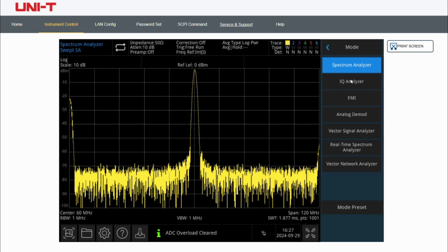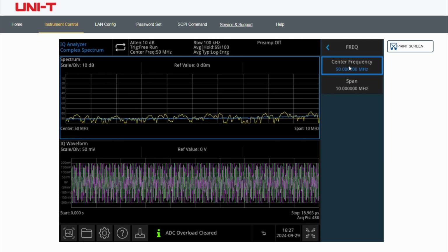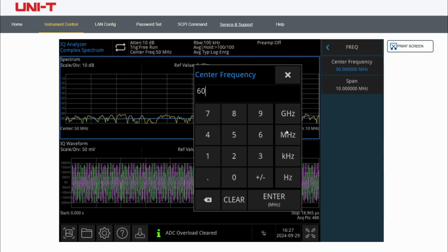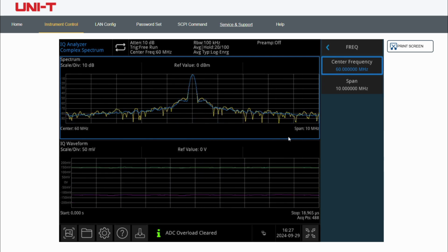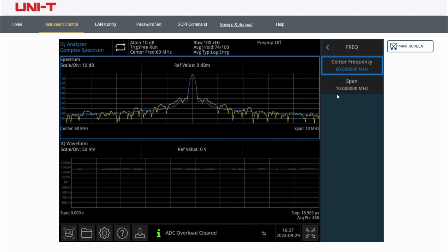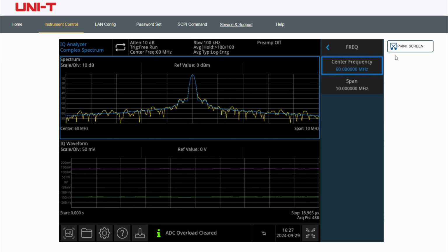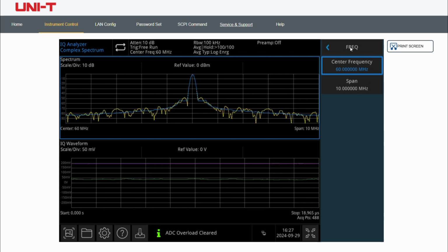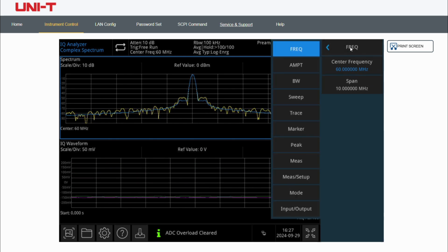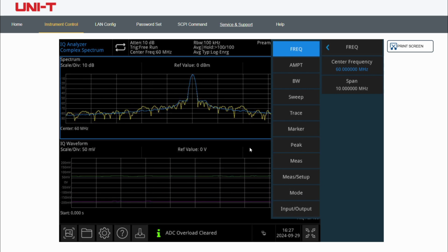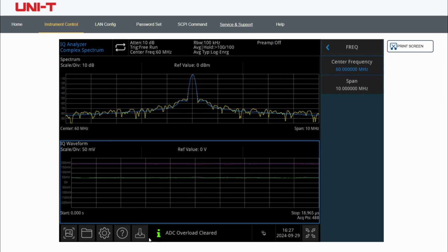What is the role of the IQ mode? IQ mode is capable of measuring both frequency and time domains. In normal spectrum analysis mode, it just scans the signal over a frequency domain. IQ analysis usually uses the hardware chain of the entire spectrum analyzer. There is no excessive data processing such as a digital demodulation process. So, the IQ data is raw compared to the analysis data displayed on the screen of the spectrum analyzer, especially when analyzing a very complex modulated signal.